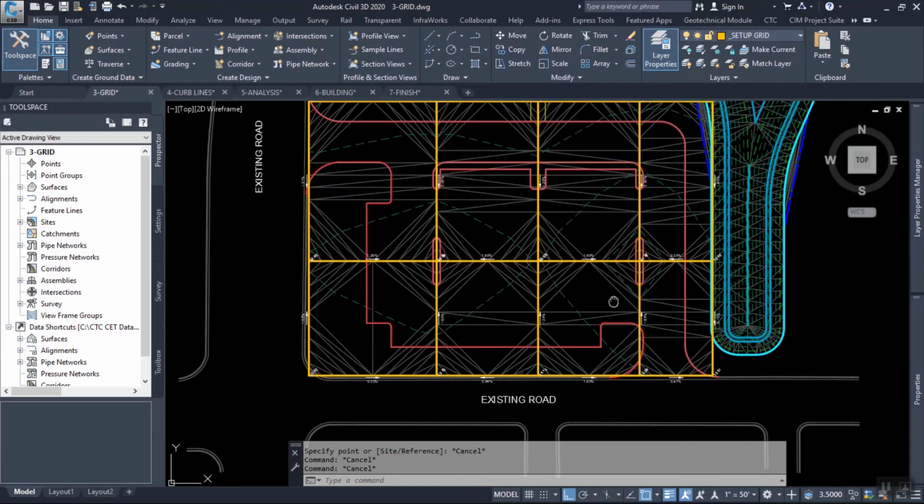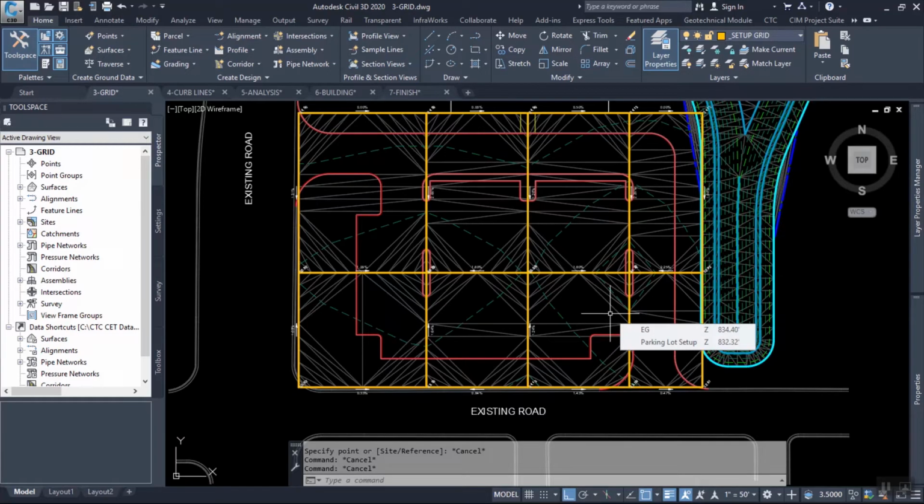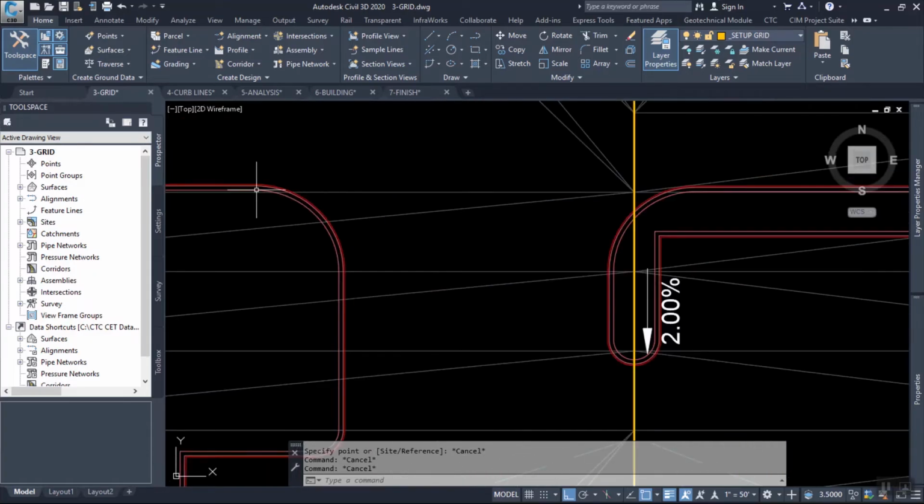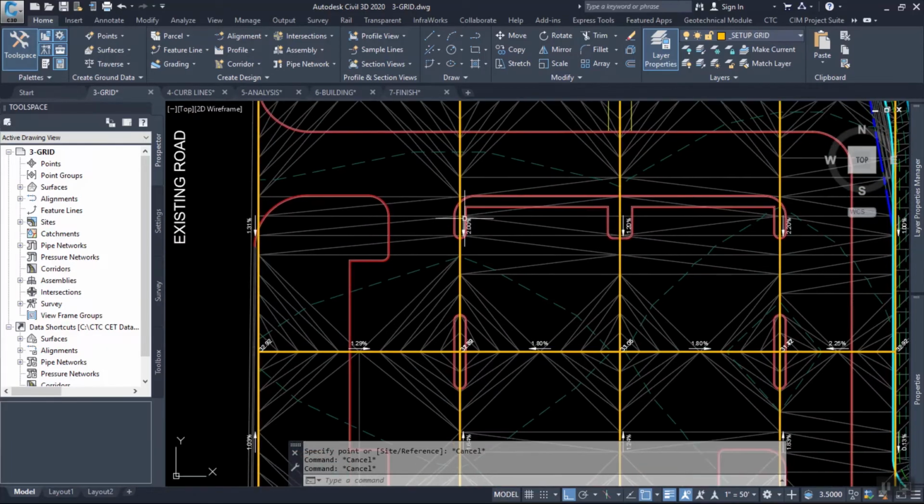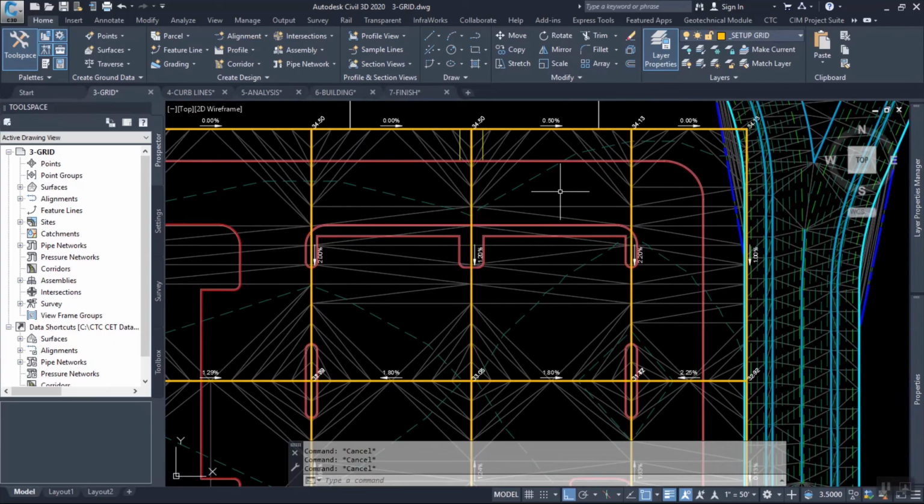Okay. The setup surface making sense so far? It's pretty simple, right? But you've got to think in terms of, don't think in terms of this point right there at my back of curb, and then this point, and then this one. Think in terms of where am I draining to, where am I draining from, where do I have to tie in, right? What's the building at? Think of those kinds of things. Every site's different, right? So there's a lot of creativity there. Frankly, I think site grading is probably one of the hardest things in Civil 3D to do because every project is different, right?